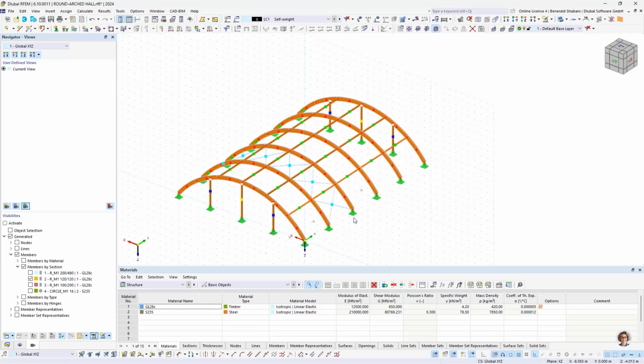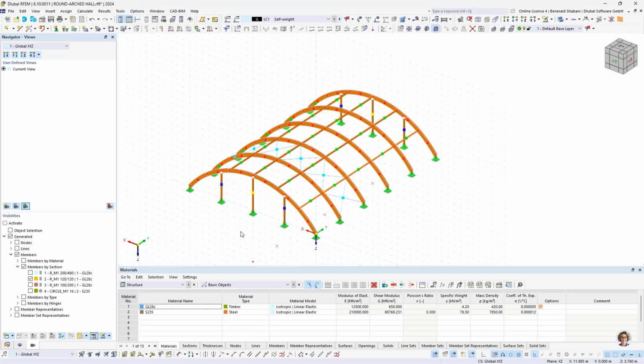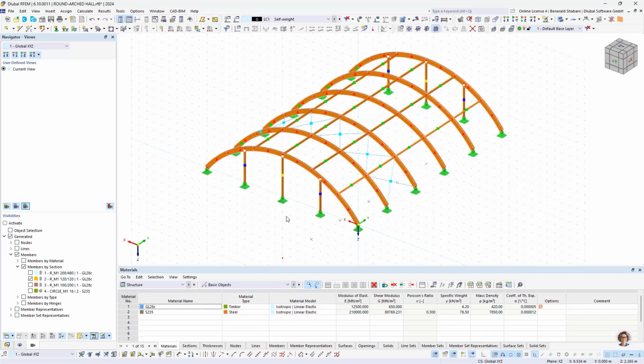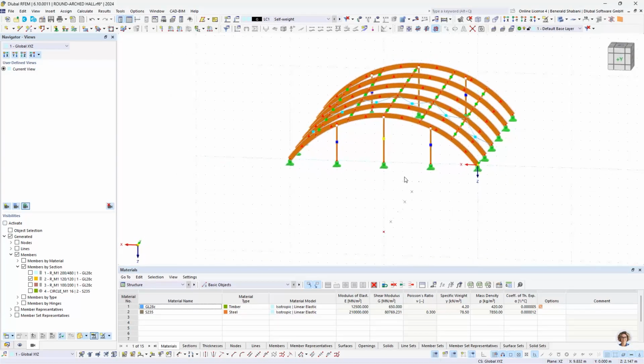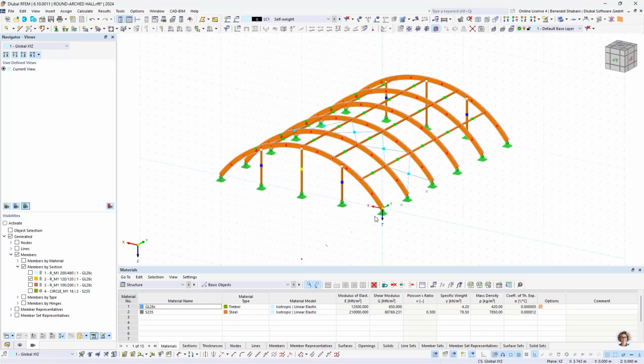Because of the roof construction, there are triangular and trapezoidal loads that apply to the gable supports. Without the load transfer area, we would have to apply the triangular and other types of loads individually. That would be a waste of time, and it would also be a lot harder than just putting it with the load transfer.